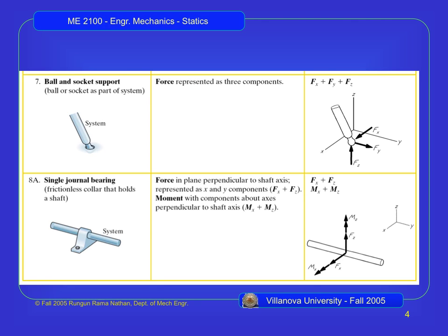All right. So look at the system here. Don't even look at the diagram here. Look at the system. Which way do you think this is able to rotate? Can it rotate like this, you think? No, it looks like it's locked in there, right? Can it rotate like this? Which way can it rotate though? About its axis. See how I'm turning it? That's what that's made for. So it can rotate this way. So notice there's no moment along this line. There's no moment preventing it from rotating this way. But it is prevented from rotating up and down. Okay, it cannot do this and it cannot do this. This rotation is prevented by this one. This rotation like that is along that axis. It's hard to visualize, so I'm trying to show you with these diagrams.